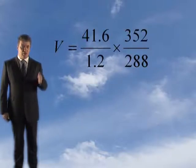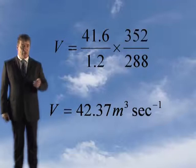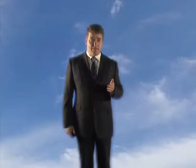If you'd have put those in, you'd have worked out your volumetric flow rate is 42.37 metres cubed a second. So you need to extract a total of 42.37 metres cubed a second. So that covers step 6.